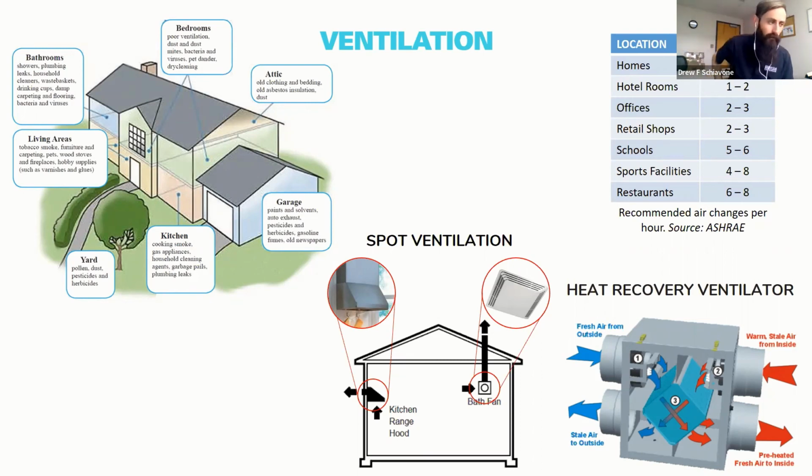But you can have that formal test, an energy audit, done and see what your airflow rate is. The ASHRAE standard for a home is between 0.35 and 1 air changes per hour. ACH is air change per hour. Again, you'd need a professional to evaluate this for you, but that's what you'd aim for. The lower end is 0.35, which essentially means that 35% of the old stale air is exchanged every hour. So 0.35, or 35%, of your old air is exchanged with new air every hour.